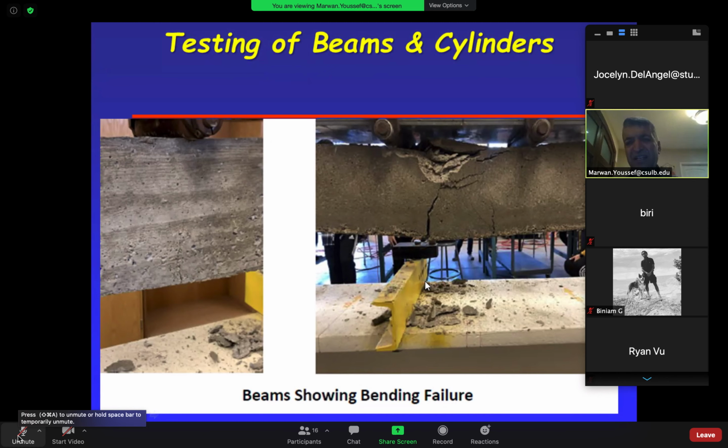Does that make sense to you now? Look at that. The crack from here to there, what happened to it? It opened up. That means something is elongating it. Something is stretching it out. What is that? Tension or compression? That's tension. So this is the tension at the bottom, compression at the top. Between the two, there's an imaginary line here we call the neutral axis. Above it is compression, below it is tension. And that's that C distance we were talking about. Remember the C? When we did the strain diagram, that's the C distance from the neutral axis to the top, and C from the neutral axis to the bottom as well.